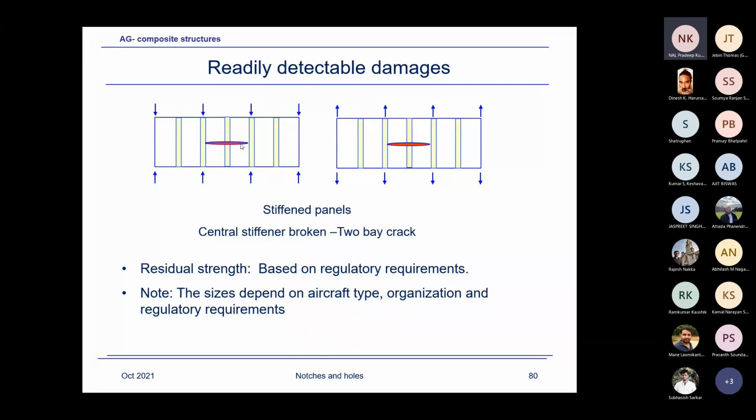But for metal, that is not that important. Yes, metal is different, because the crack will close under compression. Sure, I appreciate that. But in composites, it's not that simple. Yes, because there are different layers and that effect will be there. Usually we find the compression strength to be lower than the tension strength. Of course, it depends on the material too.